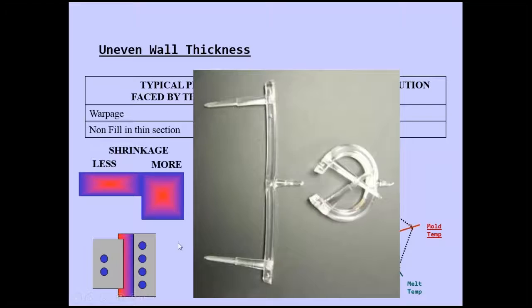And that's exactly what happened here. If this side is getting hotter and the other is now very cold, what you should do is change this temperature to match that temperature. So now both temperatures are the same. When this runner comes out, it's going to stay flat or flatter. But that's definitely not what happened. He had an 80-degree difference between this side and this side. Definitely not a good thing, just to compensate for the bad mold design. Actually, the mold will get damaged, not just the parts. You'll have other issues with it too.